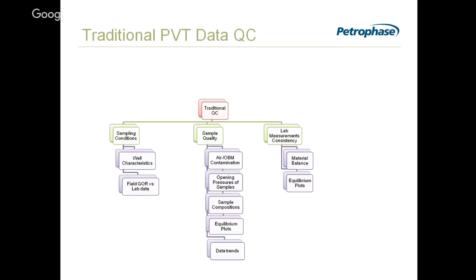The overall mass balance is useful, but supposing something is wrong, supposing, I don't know, you get less C5 out than you put in, well, where in the study has it gone wrong? We don't know. It may be we have an erratic point, but because of the stepwise nature of the CVD, errors from one depletion level cascade into the next and the next and the next. And people plot the K values out of a CVD experiment and say, well, it looks about right, but really we've no way of telling. This is why equilibrium flashes are better, because you can nail every phase and get a much better description for your equation of state. You don't have this progression of errors spilling out from one level to the next.